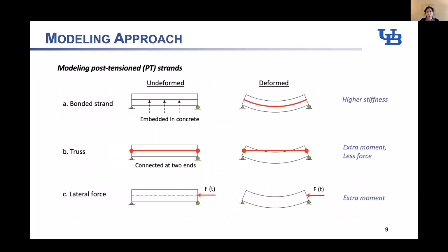Okay, in terms of post-tensioning, we couldn't define contact property. So these are unbonded. I forgot to mention this: in the test, the post-tensioning strands are unbonded. So rather than directly modeling the actual ducts and post-tensioning strands, we considered again 3 different alternatives. And we know that these 3 approaches will give us an upper bound and lower bound of what would happen in reality.